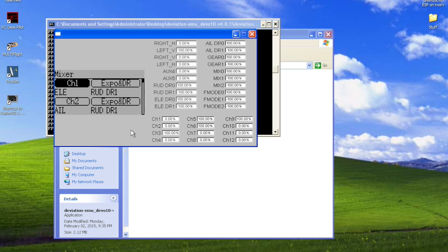Certainly with something like RealFlight, once you have all the controls set up properly so that the radio is transmitting them, you can select which channel you're transmitting on to correlate to what channel it needs to be in the simulator. But the principles are the same. So if you need your throttle to be on channel 1, then simply execute the correct channel mapping.